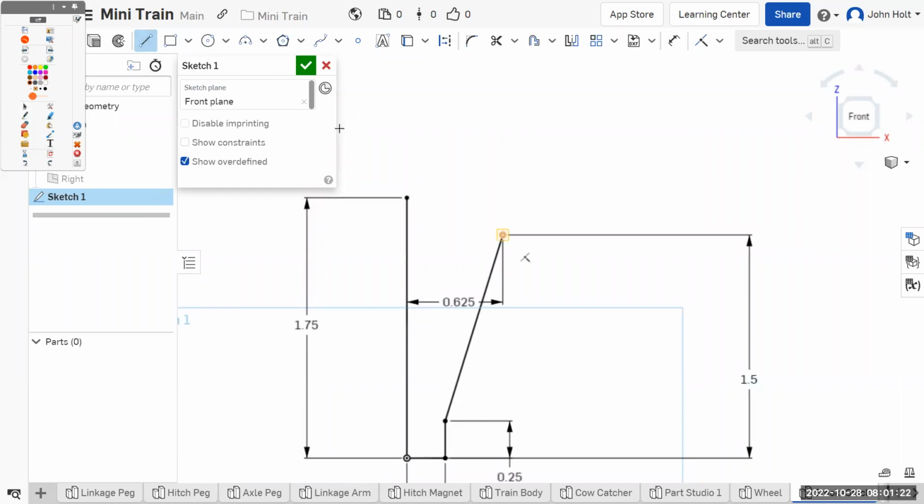So we're just going to draw a line, and if we had construction lines, let's see, do we have construction lines? Yeah, you can use a construction line. You can actually use a regular line for this. It doesn't really matter, just so long as you snap it to vertical. And then we can draw a line from here going roughly the direction. And you can try to line it up by going like this and then going over, but it's not critical at this point. You do need to just draw it up in that direction. Then we can dimension the angle between this line and this line, set it to 15.